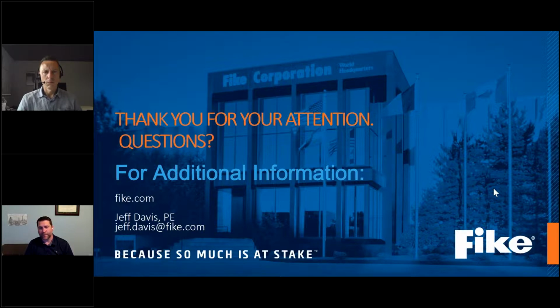so it's a very good idea for US companies to adopt that approach of identifying your zone locations. If you're not a European company, you're probably going to be using the class division system. So it's at least documenting and identifying these maps for where you have a Class 2, Class 1, Division 1, Division 2 location, where at the very least you're doing that. We see more of that, it's a very good practice, and we'd recommend it.